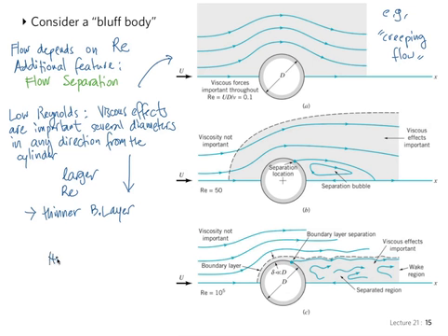For this case of even higher Reynolds number, you will have a thin boundary layer, like in the case of the flat plate. But there is a point beyond which there's flow separation. So even though the boundary layer is very thin, there's still a region that extends far away from the object where viscous effects are important, and this is due to separation.